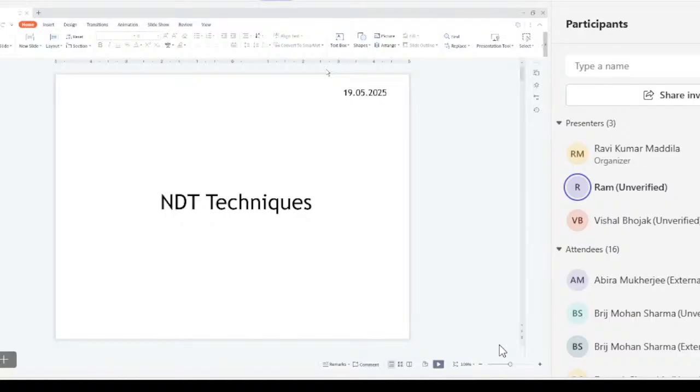I'll get back to you in your next slide on how to understand whether a particular defect is tolerable or not. One important factor to understand is, as I said, the microstructure decides the properties. For destructive properties like tensile strength, fatigue strength, and creep strength, you use conventional destructive testing. But the problem with destructive testing is that you destroy the sample.